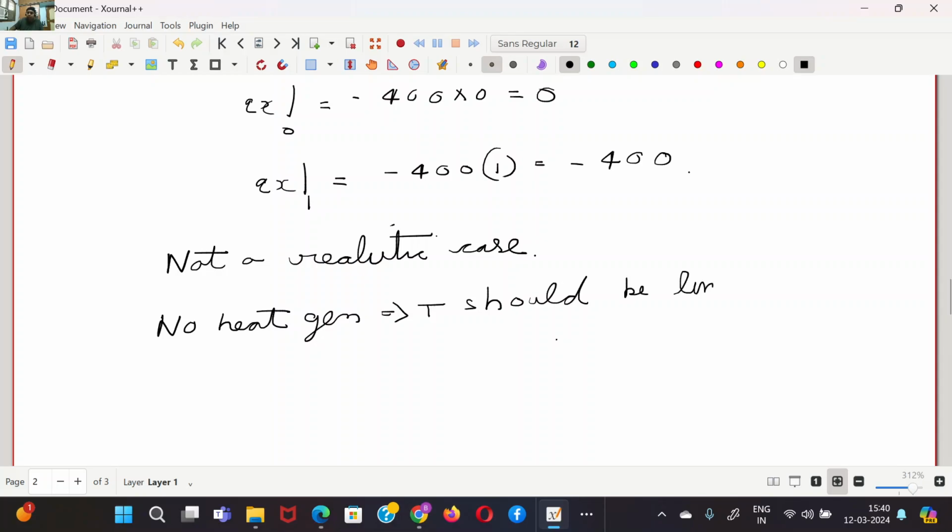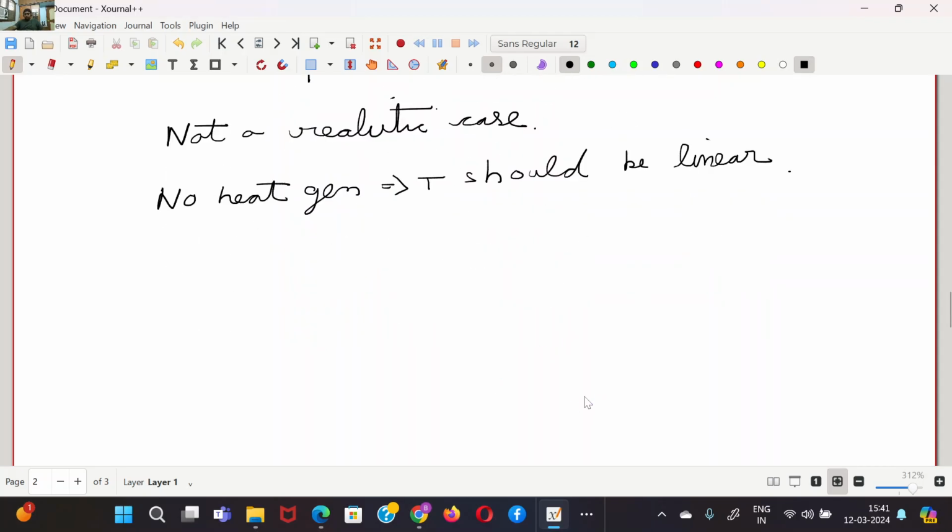Maybe next class onwards we'll start solving problems like how we did for fluid flow. We'll take some transport problems, maybe conduction through a slab or through a wire. We'll see how to apply the equations of energy, then the boundary conditions, to get the temperature profile in this case, right? So yeah, this was an example. Now what I want to come to is that for the derivation of the Navier-Stokes part, we took the momentum balance. In this case, we'll have to do an energy balance, right?